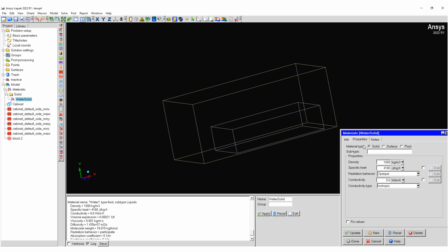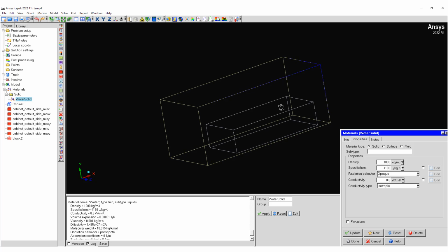One thing that's helpful to point out is that right now I just made the walls of this trailer polystyrene, but we can also make it a composite material. We can change any of these values from isotropic to orthotropic, anisotropic, biaxial, or shell-orthotropic.